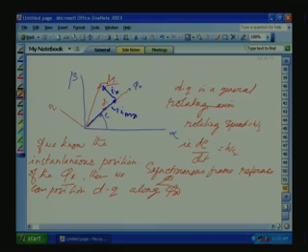So, if you know psi r and place the dq axis along psi r, that is, d is all the time, for any dynamic conditions, placed along psi r, then the component of IS along d will be proportional to the rotor flux producing component, and any component perpendicular to that one will be the torque producing component.